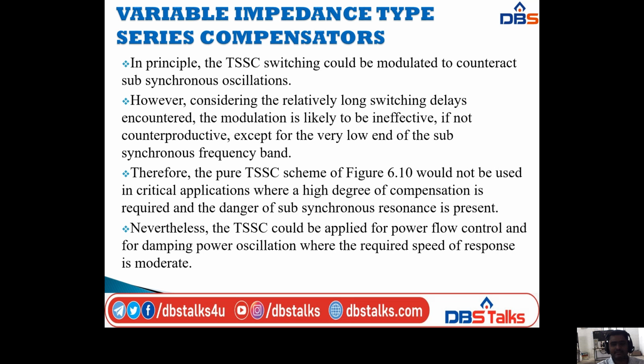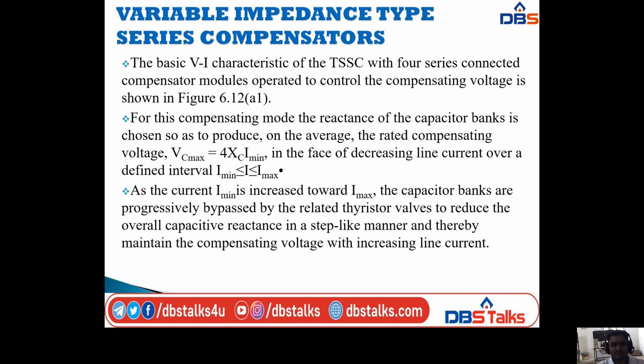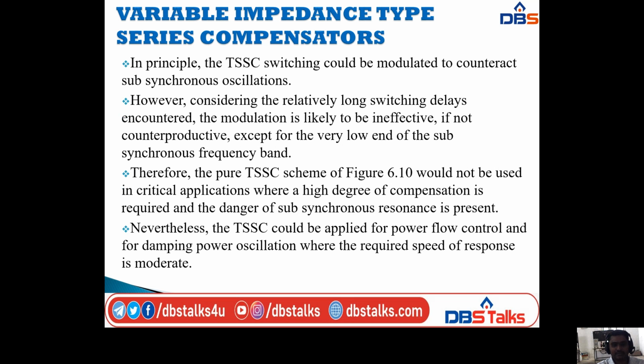Therefore, the pure TSSC scheme of figure 6.10 would not be used in critical applications where a high degree of compensation is required and the danger of subsynchronous resonance is present. Nevertheless, the TSSC could be applied for power flow control and for damping power oscillation where the required speed of the response is moderate.